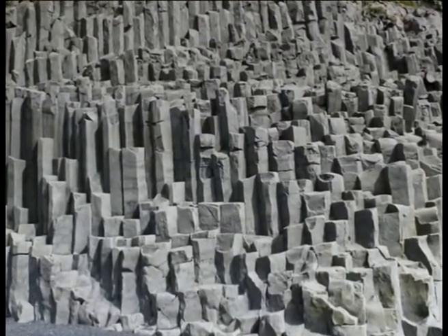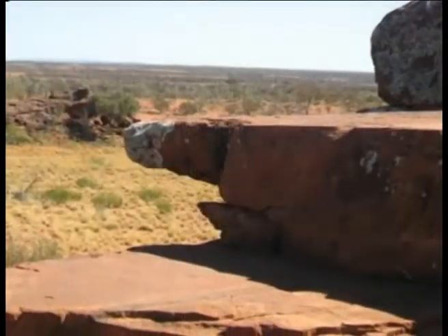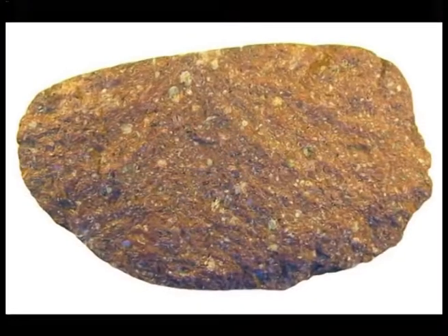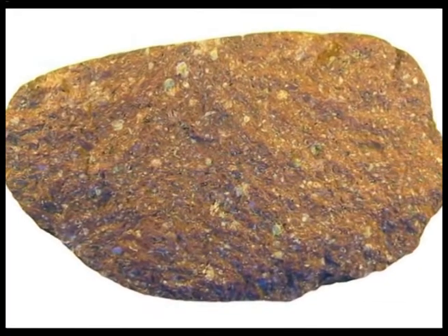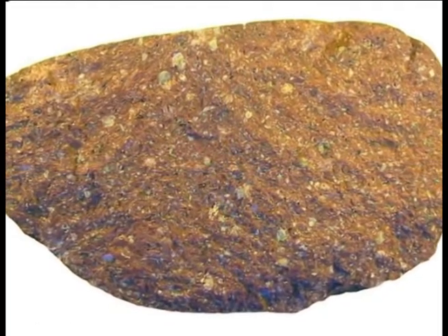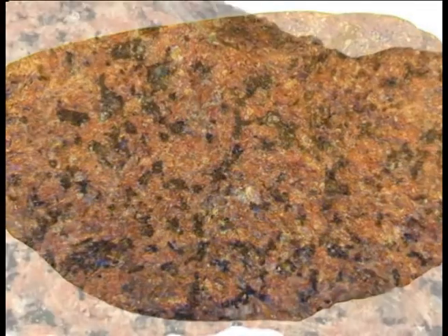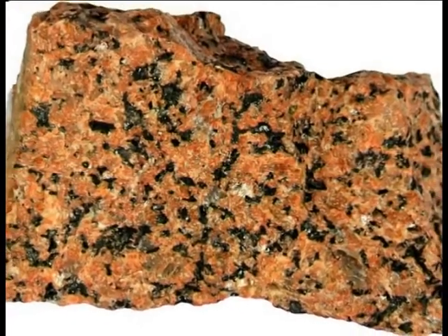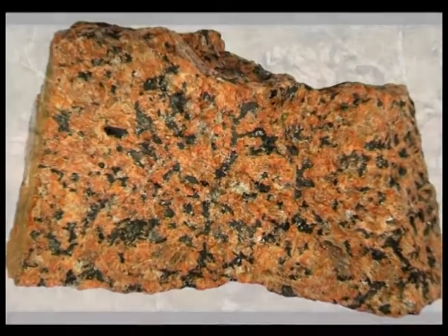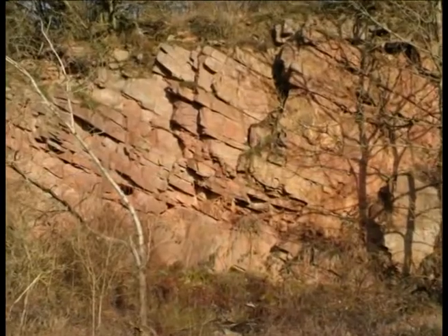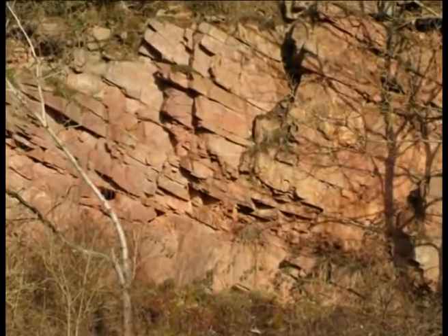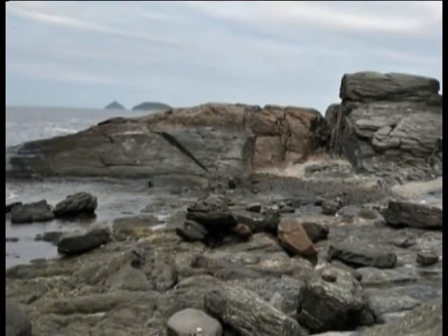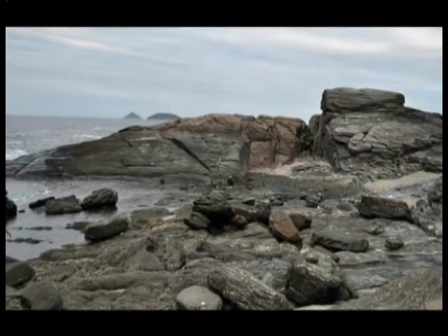Frost causes disintegration by expansion of water on freezing within the rock pores. In the case of fire, it is unequal expansion in the different mineral components and also at different depths from surface inwards. This effect becomes more pronounced when the rock is first heated and then suddenly cooled by water. Heavy stones including granites crumble to pieces under such a treatment. Only compact and massive sandstones and quartzites will behave reasonably well in fires and heating places.